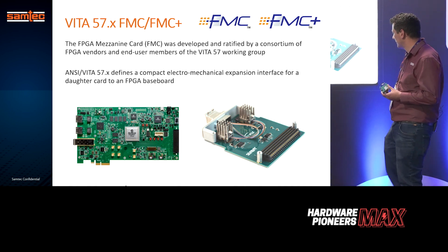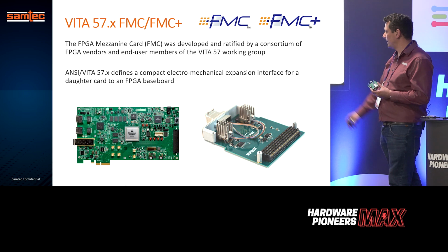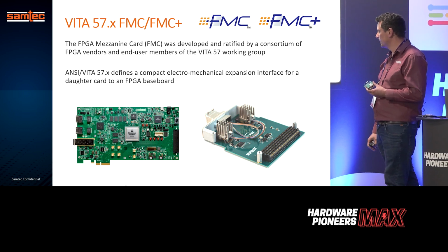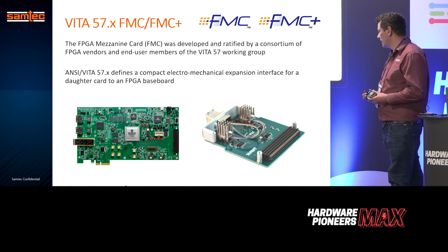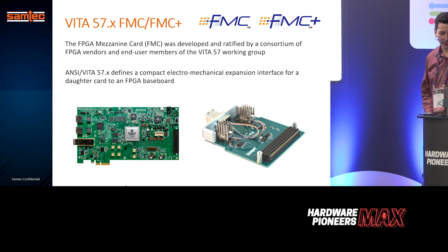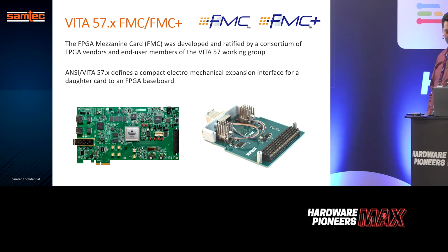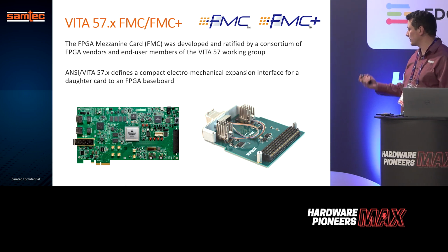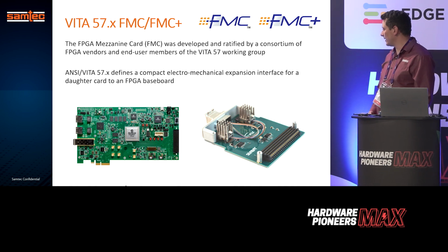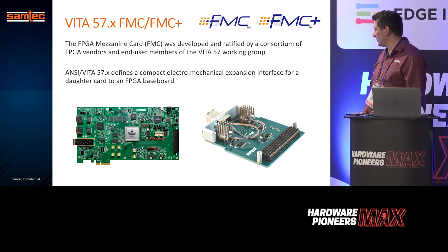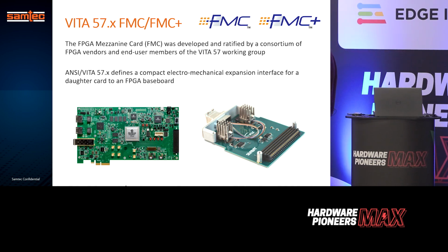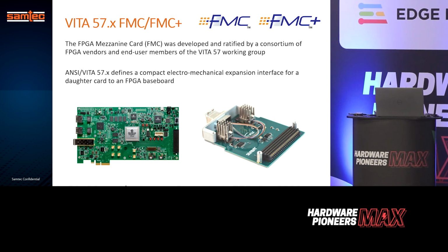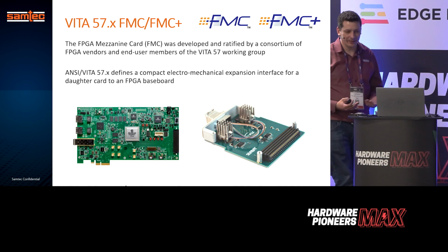So this is a different example, but this is the typical architecture that you see for development. You have an FPGA. You want to test, for example, an optical functionality. So you just get a standard pinout PCB. It will have your power, it will have your high-speed signals already defined. So every time that you plug in an FMC card, you know what you will have. So you will have a fully interoperable device.